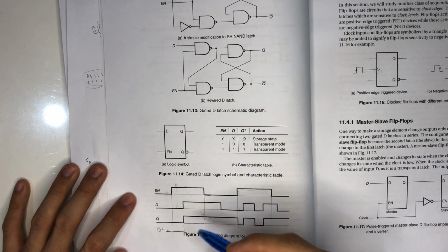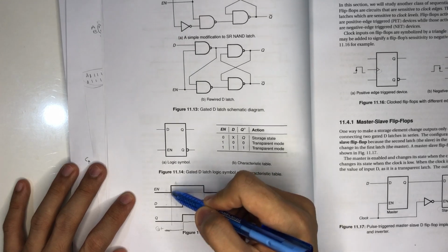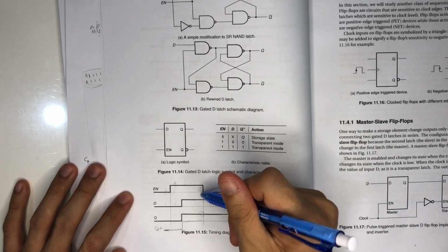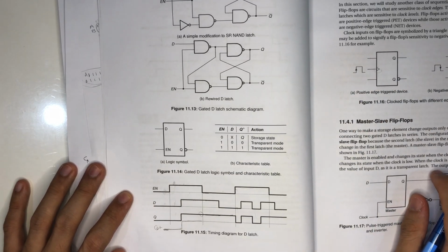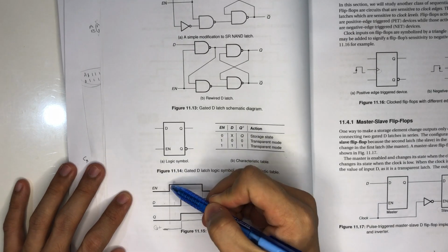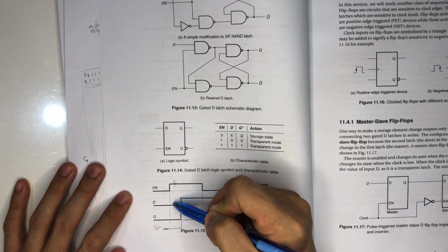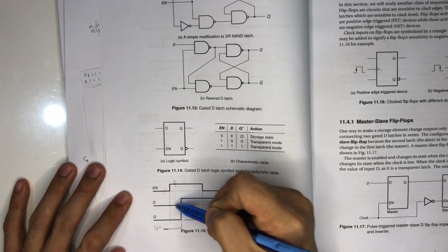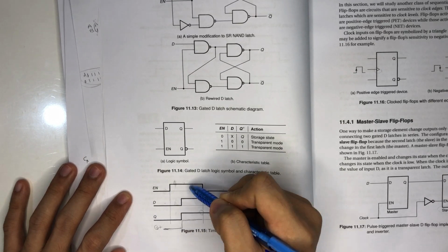So this is the timing diagram you can see and you can understand. Don't just see it like this, you need to understand what actually happened between this, and then you're able to know the circuit much better. Let's say you have enable 1 here, then you have your D is 0. What happens is the Q will just follow your D. The same with here, it just follows until here.